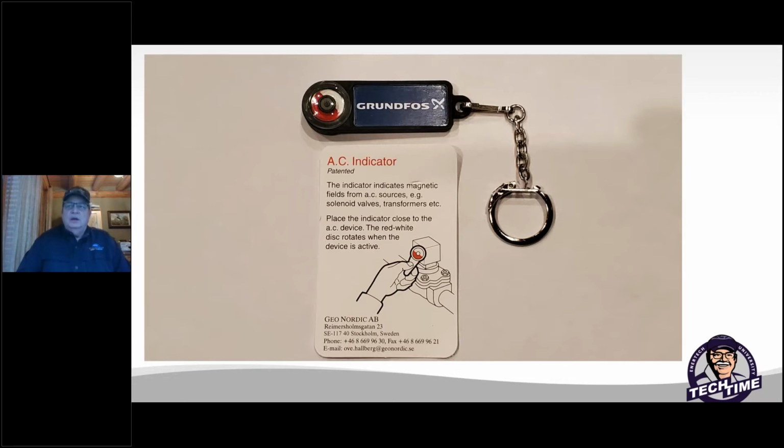The only true way is either removing the pump and looking at it, or if you have the little screw on the center of it, remove that and make sure the thing is actually spinning and moving for you. So bear that in mind. It's not a 100% guaranteed deal. Check with your gauges for water pressure flow differential across your heat pumps. That can also help you to tell if some of these pumps are not working.